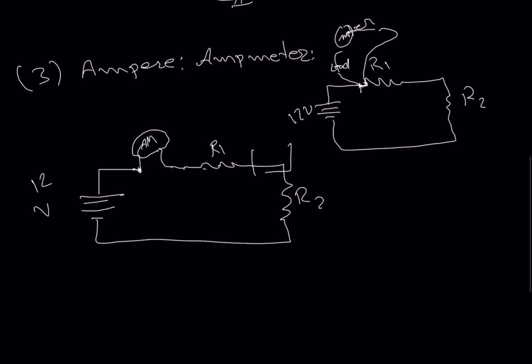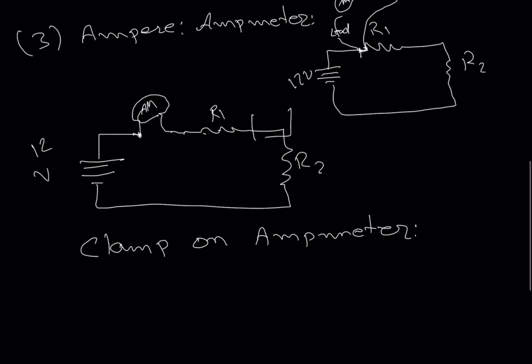And we do have a lot of different kinds of them, but if you are dealing with, for example, 3 phases, 480 volts, that's a good practice to use. A lot of electricians use a clamp on meter, a clamp on amp meter. This is a meter that has a jaw, and you can just put it on a single phase of a motor lead or a load to see how much amperage that particular device is drawing.